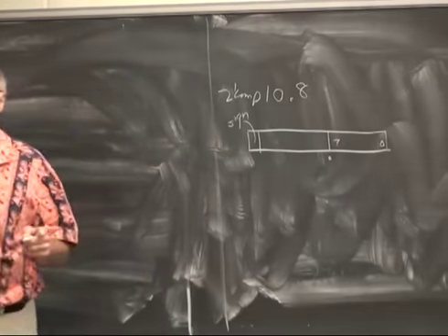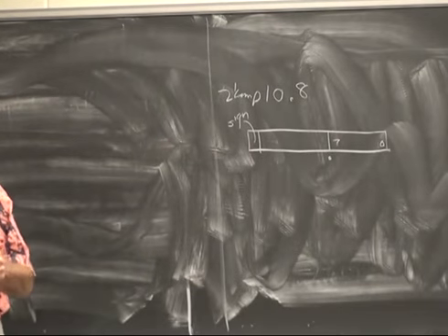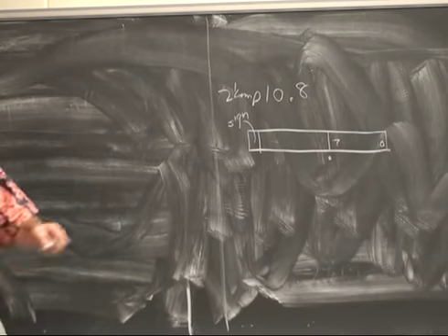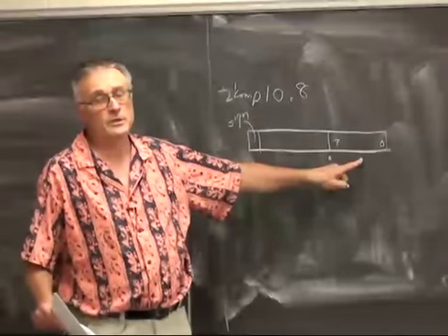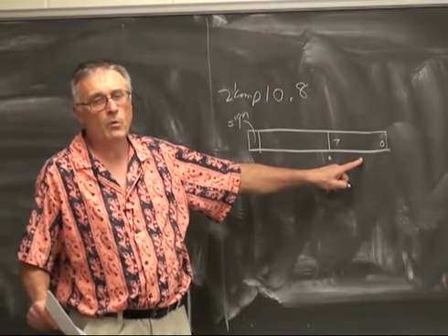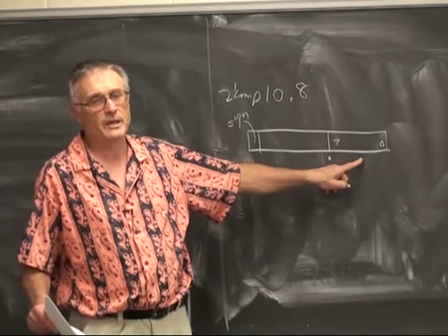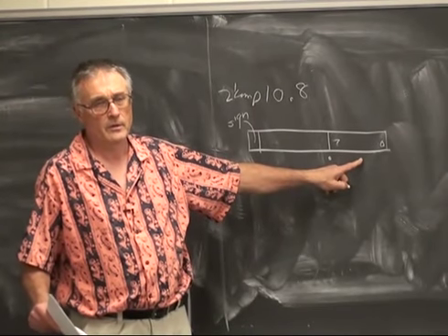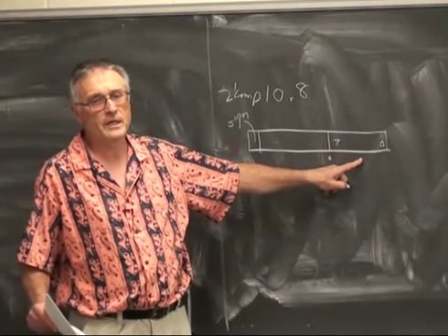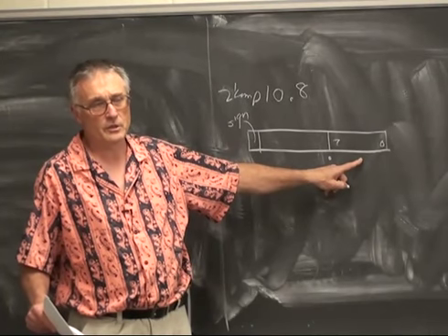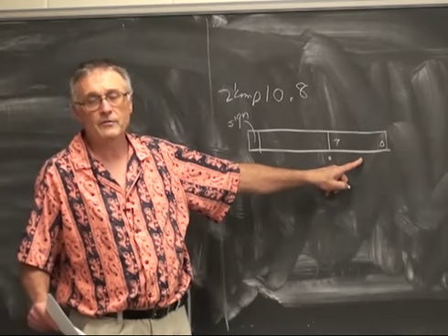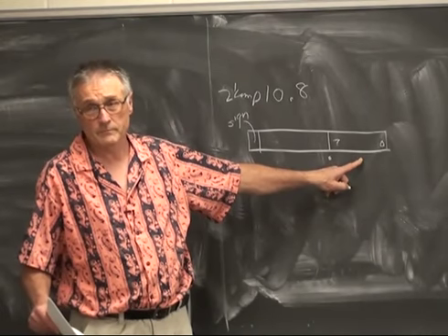What you're going to find that you need for DSP is a different format, because 8 bits of fraction just won't quite work for the filters I'm going to ask you to build. You're probably going to need 14 or 16 bits of precision, and so you're going to have to modify the multiplier.